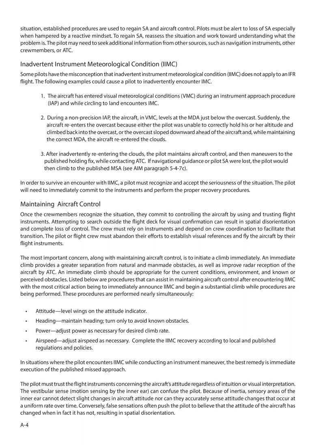Because of inertia, sensory areas of the inner ear cannot detect slight changes in aircraft attitude, nor can they accurately sense attitude changes that occur at a uniform rate over time. Conversely, false sensations often push the pilot to believe that the attitude of the aircraft has changed when in fact it has not, resulting in spatial disorientation.